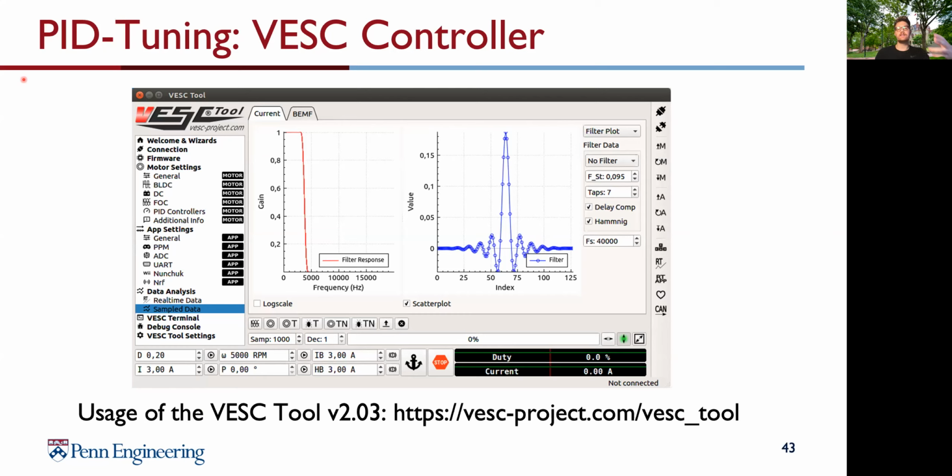And this VESC tool gives us the possibility to connect our computer with the motor controller of the electrical engine of our F1TENTH car. And after you did a firmware update, you can select the motor configuration we created for you. It's in an XML file. And what you can do, you can just drop it in here in the VESC tool, and you write it to the motor configuration.